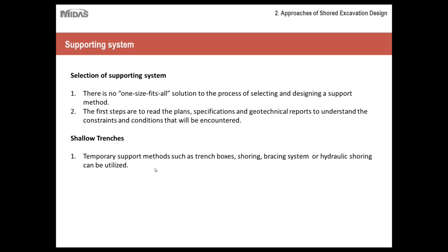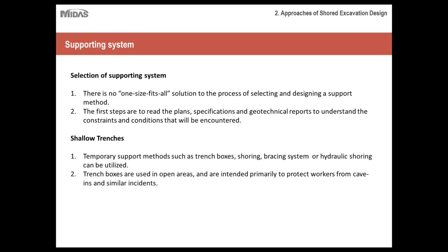Now resuming the presentation here. Let's talk about trench boxes, where we should use trench boxes and where other types of supporting systems are sufficient. Trench boxes are basically used when you have to get your workers down in the trench to set things up, such as laying of pipelines or utility lines or some fixtures that you have to apply. So the trench boxes basically support the walls as well as the soil to prevent failure and cave-ins and prevent accidents.